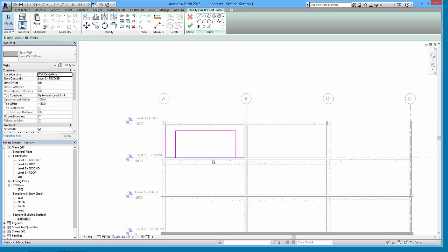To use the trim tool on this, I'm going to have to split this line. So I'll use SL, which is up here. So split element, SL. That's a keyboard shortcut, a useful one to know. And I'll split that line into 2 sections. And then I can come and use this trim. And remember to pick the ones you want to keep, not the ones you want to get rid of. And then that's formed this profile in elevation. And then I can say, OK.